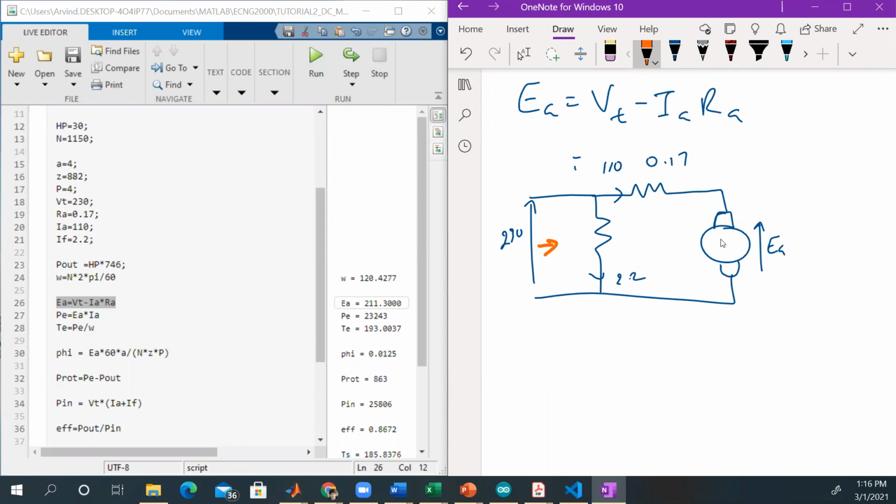Some of the mechanical power goes into friction, some goes into moving the mass of the rotor itself, some goes into windage. And the word is windage, not windings. It has nothing to do with windings. It has to do with wind, the air. This is air resistance. So some of the mechanical power will be converted into friction and windage.